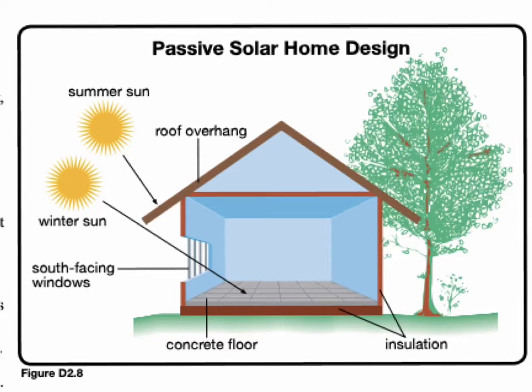So you can see in this passive solar design here, the energy comes in from the sun and is absorbed into a concrete floor. There's insulation that traps the heat, and there's insulation here which keeps this energy within the house. Now they have a low overhang because the winter sun is fairly low, and the summer sun might be too hot, so you don't want too much energy coming in; it restricts the amount of energy coming into the house during the summertime.